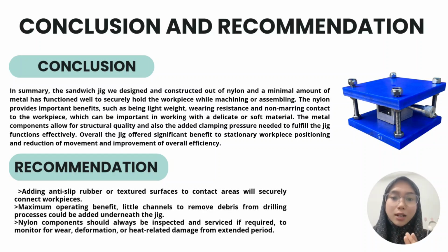For recommendations, adding anti-slip rubber or textured surfaces to contact areas will securely hold workpieces and provide additional protection to fragile surfaces when drilling. Furthermore, for maximum operating benefit, little channels to remove debris from the drilling process could be added underneath the jig. This small adjustment allows debris to be removed from the jig, keeping it from building up and causing inaccuracy or premature wear on components if chips get wedged together.